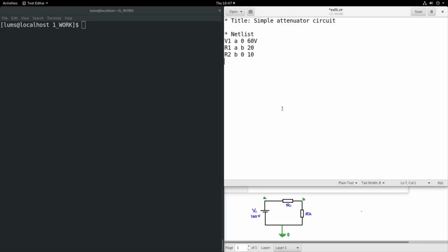Sometimes it becomes repetitive and cumbersome to write and type the control commands in the NgSpice workspace. It may be a good practice to place it in the .cir file itself. So what we will do next here is place the control commands in the .cir file itself within the control command begin and control command end statements.